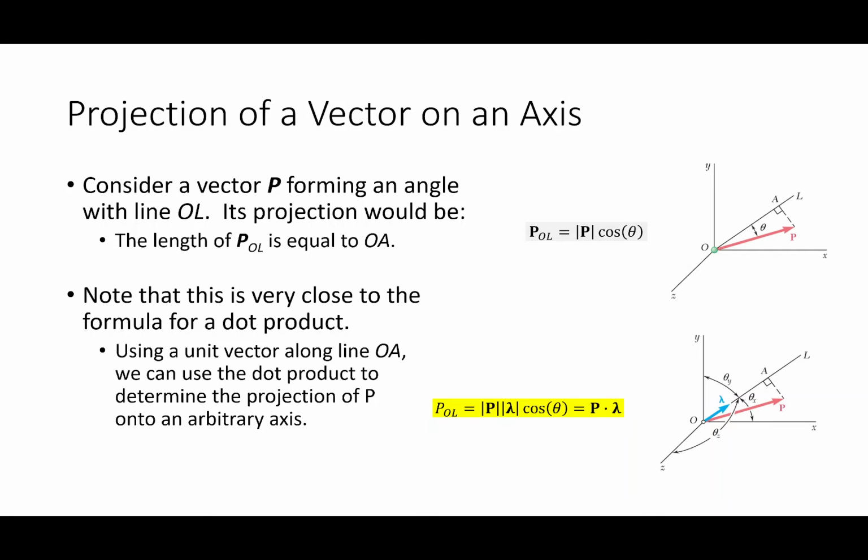And so what we're trying to do is isolate how much twisting that element has to withstand so that later we can figure out, does it need to be made out of aluminum or brass? What does the diameter need to be? How thick does the wall need to be so that it can safely resist that torsion? But in order to do that, we have to isolate, I've got this moment in 3D, how much is acting about that element. Does that make sense? So that's why we're doing it. We're not doing it just because. There is a reason. Does that make sense?